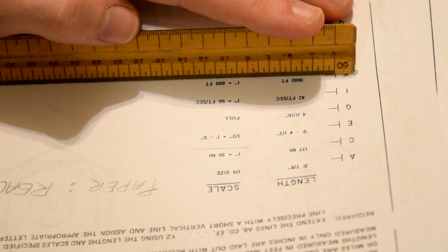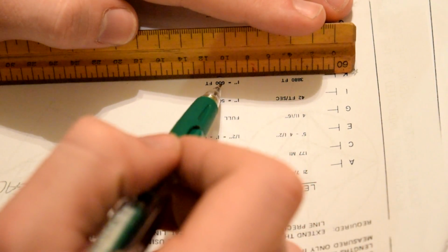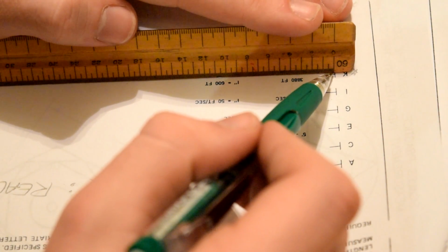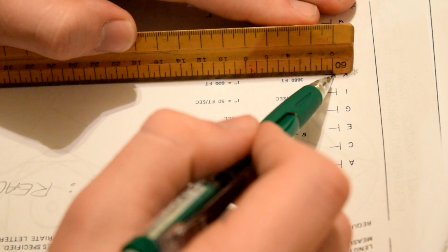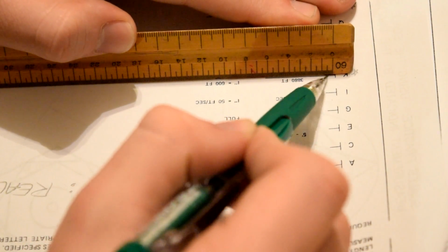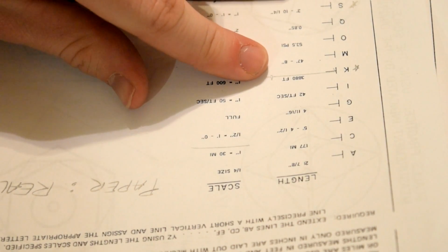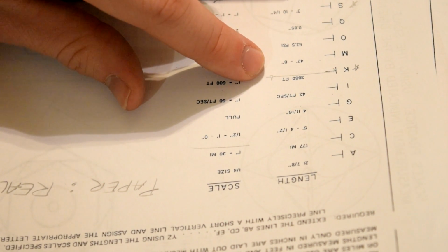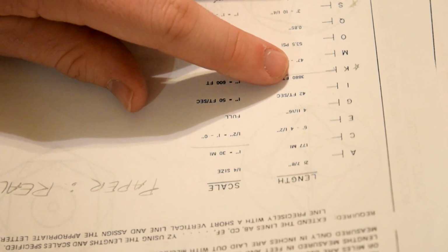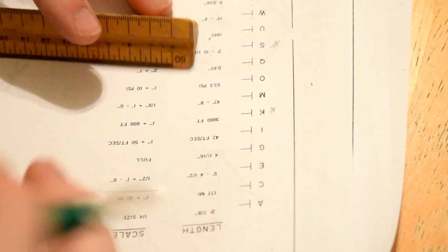3,880 feet long. Since I know that 1 inch here is 600 feet, if I were to draw a line out to the 6 here, where that cutoff is at the 6, I know that that line on paper is 1 inch, but in reality that's actually 600 feet. So since I'm drawing a line that's almost 4,000 feet long, it's going to be considerably longer than that line. So I'll erase that one. Okay, so here we go.